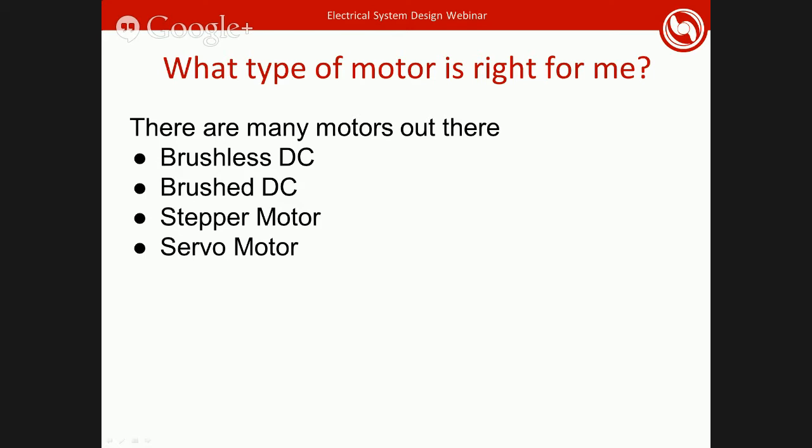Those two types of motors we use mainly for driving between tasks and really control of our overall vehicle. If you want more fine control, things that we've looked into are stepper motors or servo motors. The difference being a stepper motor will give you relative positioning. It'll move by incremental steps. And in order to hold a position, you need to constantly apply power to it.